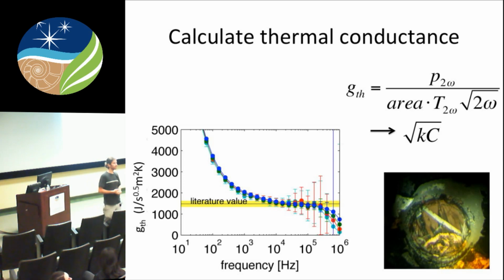Raja: In the high frequency region, you have a lot of error, right? So how do you eliminate that if it's not due to electronic interference or something, the oscillations? Well, the blue points, actually, the error bars aren't so large. And those were the highest driving voltage. So that's really the simple way, is to drive the voltage.